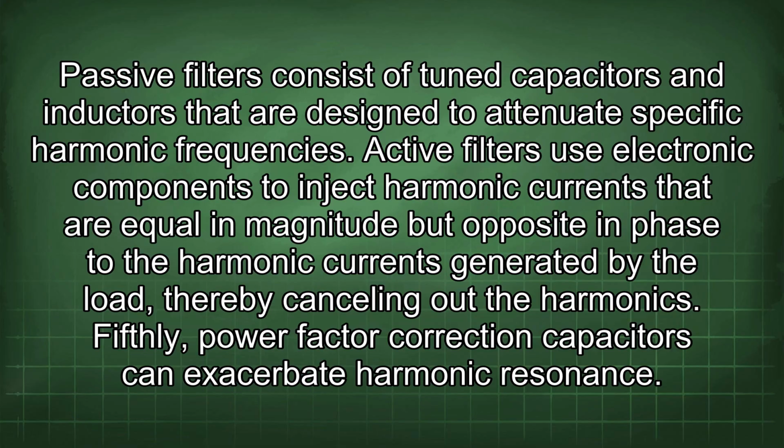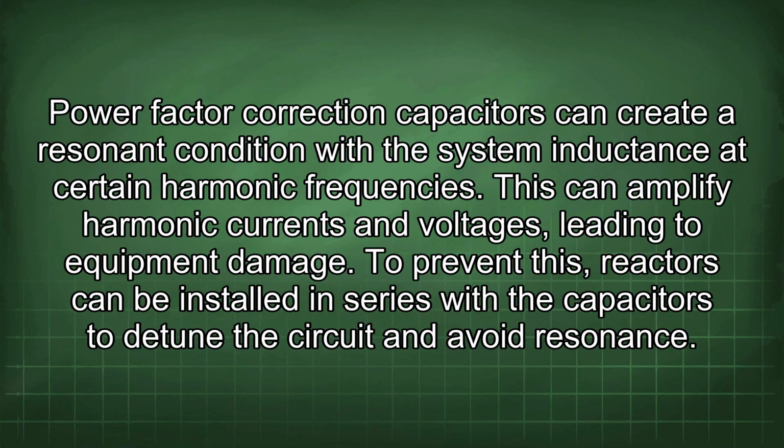Fifthly, power factor correction capacitors can exacerbate harmonic resonance. Power factor correction capacitors can create a resonant condition with the system inductance at certain harmonic frequencies. This can amplify harmonic currents and voltages, leading to equipment damage. To prevent this, reactors can be installed in series with the capacitors to detune the circuit and avoid resonance.